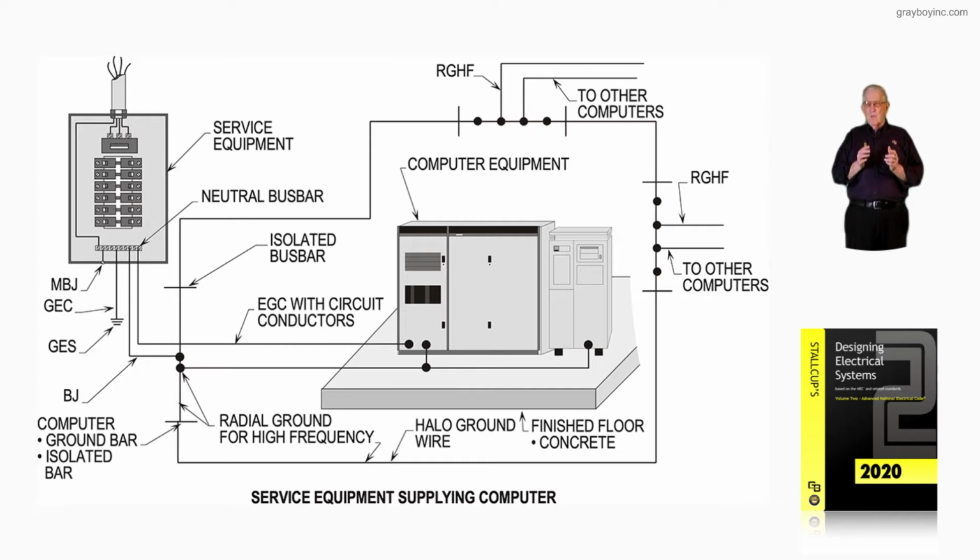If we're looking at a raised floor, we would go to 645.5(D) as in dog. But now for a non-metallic spacer or fitting, it shall be listed for such use, and we would look at 250.6(D) as in dog, 645.15, and 408.40 exception if it's applicable.